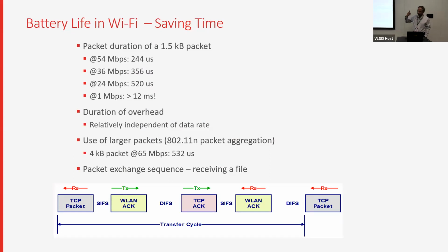And in any system, there's always noise. Even though there is no interference, nobody else is talking, every system has noise. And what is that noise? That's thermal noise. Any device that is at a certain temperature has electrons moving randomly, something called Brownian motion. So the noise power is directly proportional to temperature.